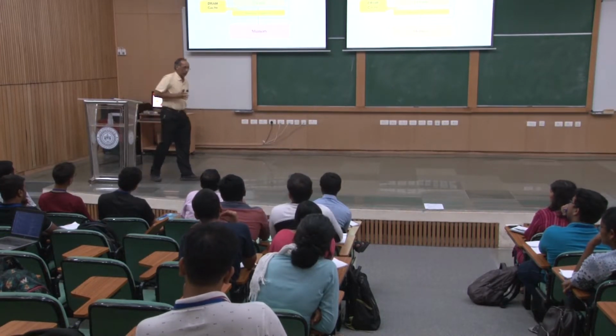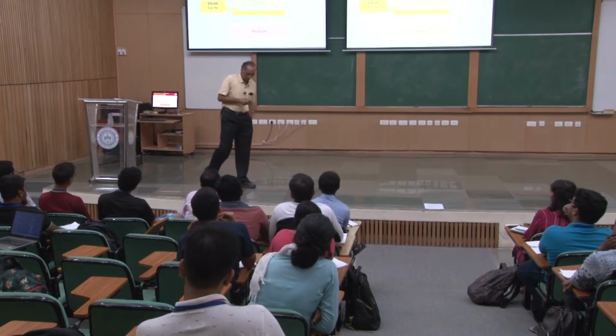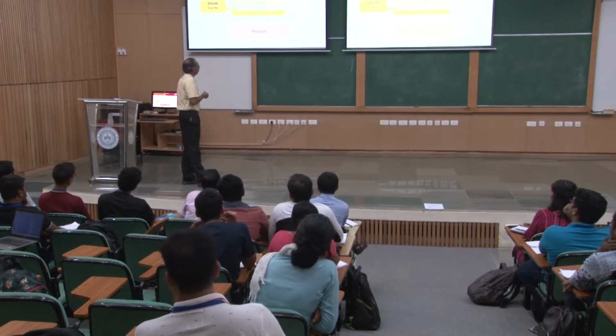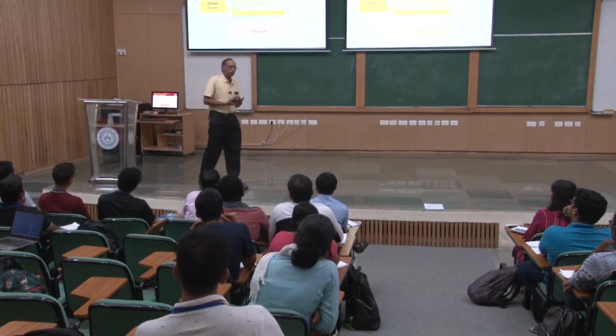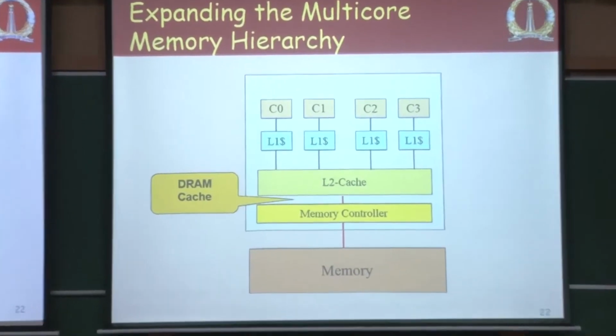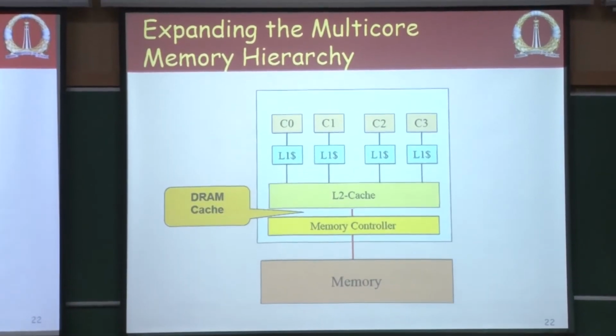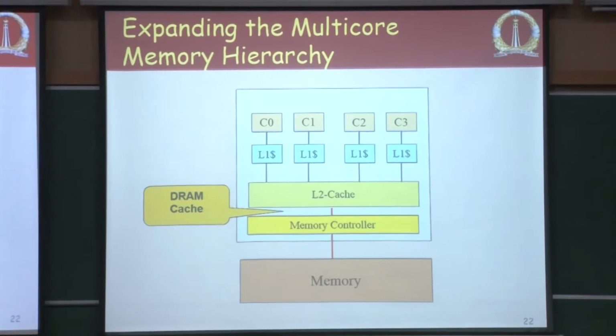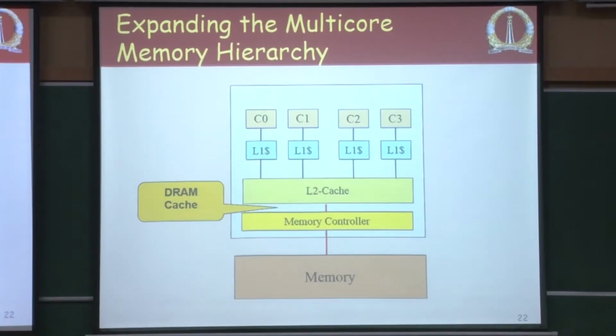Very good. So there is a huge bandwidth that I am going to get if I put it on chip as opposed to off chip. My off chip bandwidths are always limited because it is limited based on the pin counts on my device. Off chip means outside the device, outside my processor, however many pins I can get, my bandwidth is going to be limited by that. Whereas if it is on chip, I can increase the channel width, I can increase the bus width, and I can get huge bandwidth gains. And particularly it is going to go through what are called the TSVs, which can operate at a greater clock rate and so on.